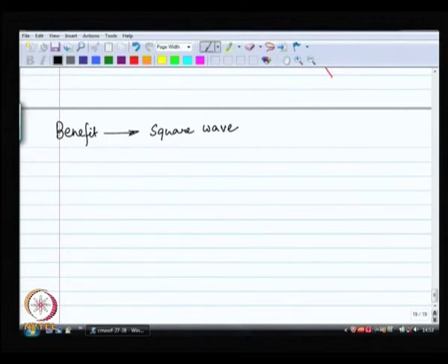All right. Why do I like square waves? I think we talked about this before. We like square waves because the noise is only the phase noise. The amplitude noise is irrelevant because it is a square wave, right. Wherever there is any noise in the amplitude, it is cleaned out because you have got plus and minus VDD or the power and ground as your voltages.